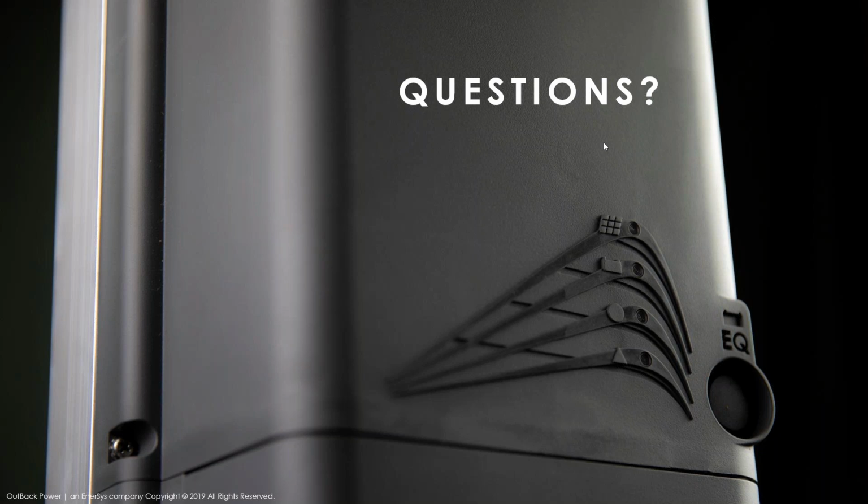So first, SunSpec Modbus is available via the gateway, the Mate 3S. So right now, we are really only recommending the Mate 3S. The FM100 AFCI does communicate a lot of data. So the Mate 3S is going to be your most reliable gateway device for this charge controller. And yes, SunSpec Modbus is available through the Mate 3S. So just like with any of our other products through the Mate 3S, a user can communicate and program and control the unit through SunSpec Modbus. Okay, all right. So yeah, the SunSpec Modbus.